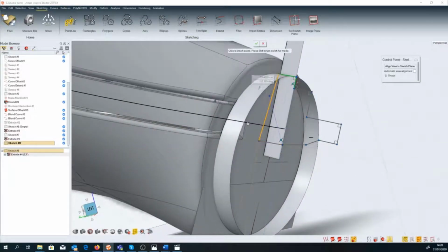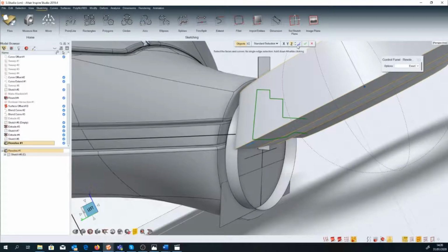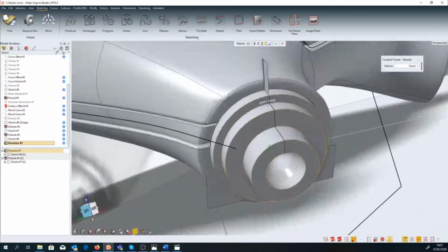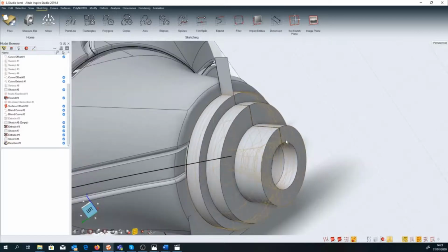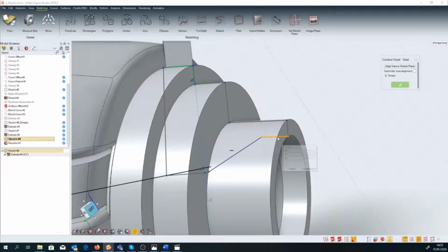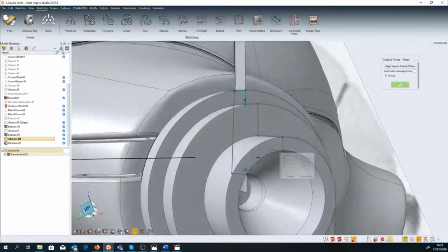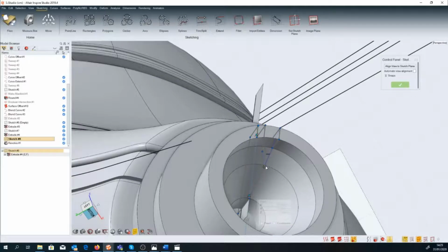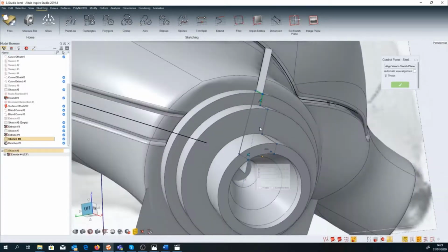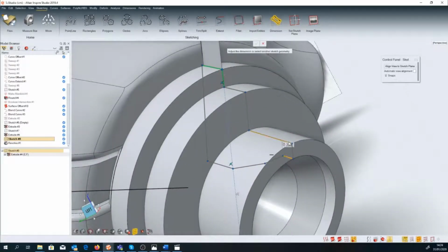Okay, final point. And now I'm going to select the profiles and the reference axis to create a rotational surface and complete the first step to create the filters. I can maintain the sketch geometries without constraint, but I prefer always have the control of the sketch element. If you change something in your model, you don't know which impact this changing will have on a sketch, not constraints.